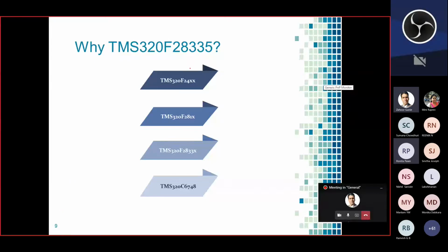So we have seen that in our control algorithm, we have a lot of mathematical calculations. For all the 5 phases, we need to do the PWM technique, also sense the VPV, IPV, and then give it to the ADC. Then from there, we need to operate MPPT, then the PWM technique. All these things should be taken care of. So for that, we have decided to use the DSP, digital signal processor, and not the microprocessor.